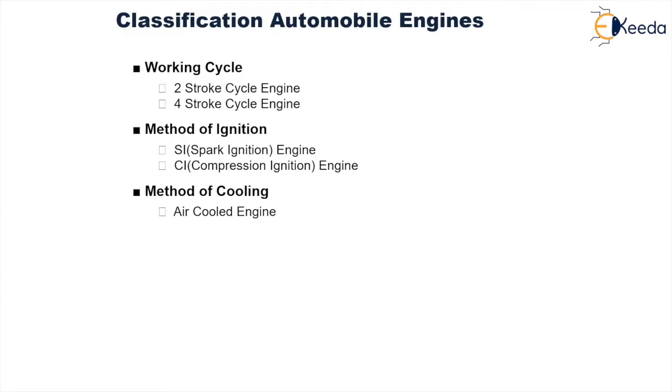These fins carry away heat from the combustion chamber, and in turn the draught of air which is passing over these fins as the vehicle moves carries away the heat from the fin, and hence the method is called an air cooled engine. But in certain cases, when the capacity of the engine is very high, an excessive amount of heat is generated, and air cooling by itself is certainly not sufficient to carry away the excessive amount of heat.